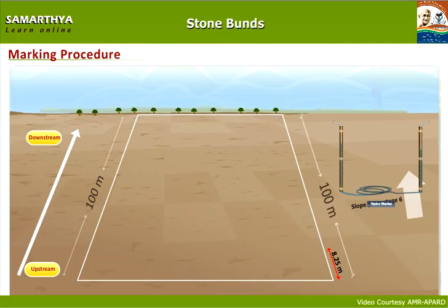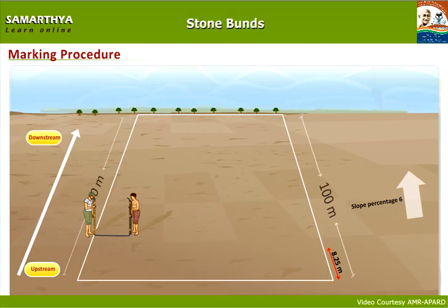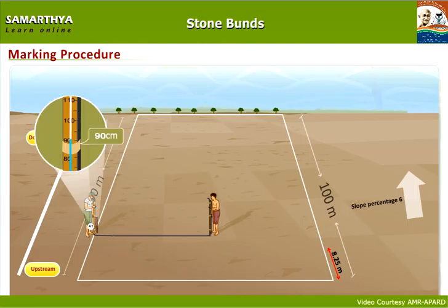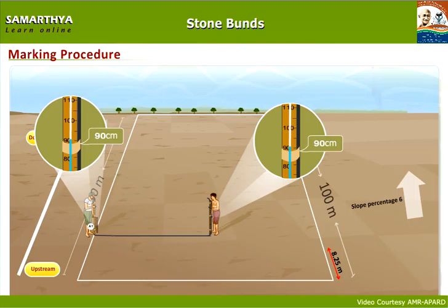We use a hydromarker to draw this line. Place one side of the hydromarker at one side of the field and mark it as A1. Starting from one side of the farm, place the hydromarker and stretch it to the second end. Adjust the second end of the marker until the water level is equal.